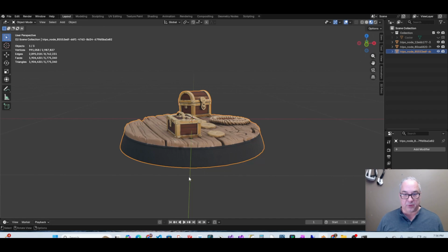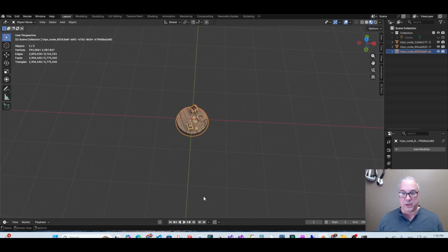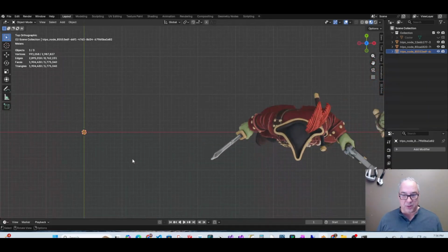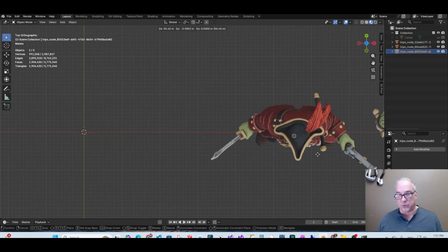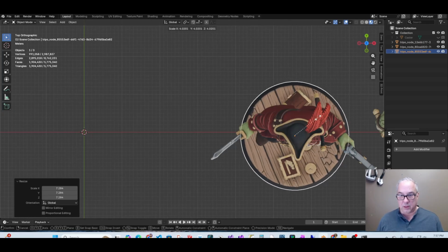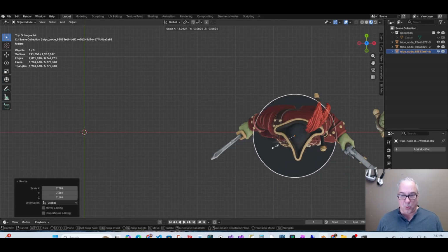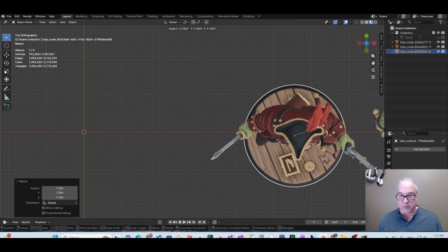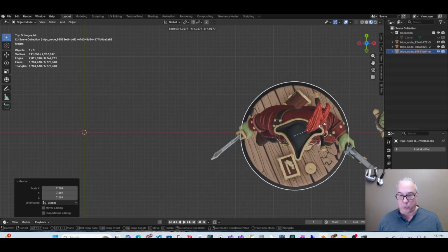We're going to tab in. I think what I'm going to do here is go into top-down mode, and this time I'm in top-down mode, so when I move stuff, it's going to stay locked to the horizontal plane it's on. I'm just going to G, and I'm just going to move it over here till it's under our captain, S to scale, and I'm just going to scale it up till it looks about right. What I did there is I actually went the wrong way, and it scaled it upside down, so I'm just bringing it back this way. There we go. I think that looks pretty good.